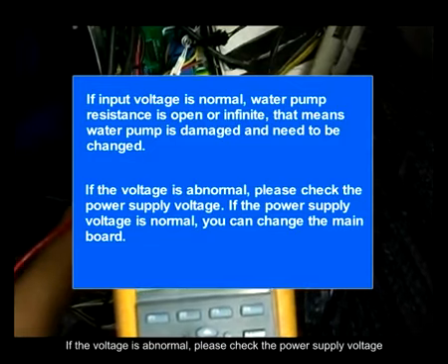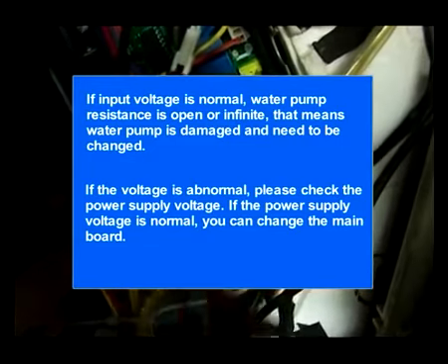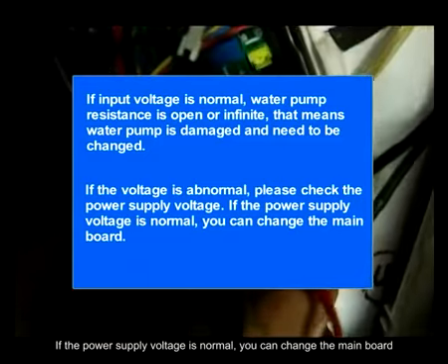If the voltage is abnormal, please check the power supply voltage. If the power supply voltage is normal, you can change the main board.